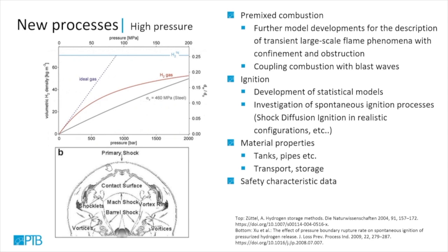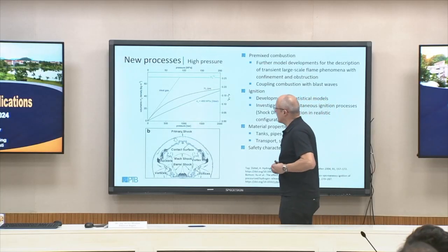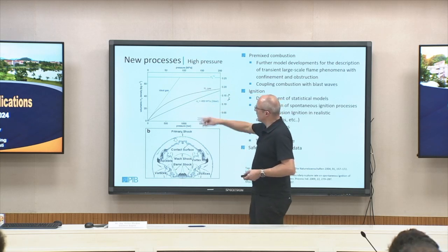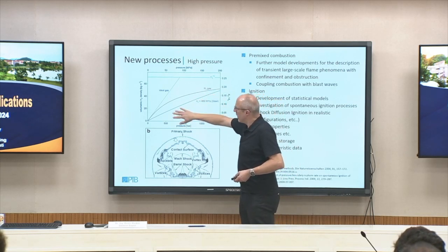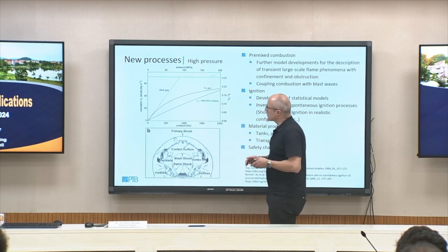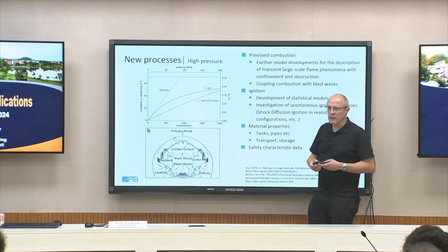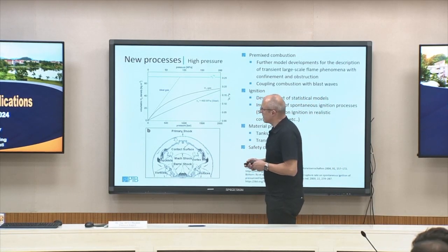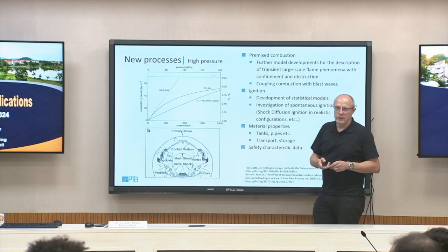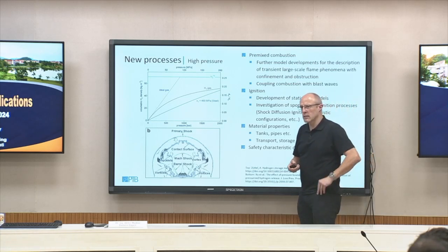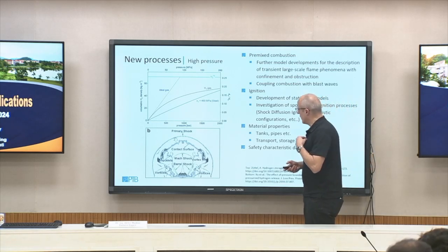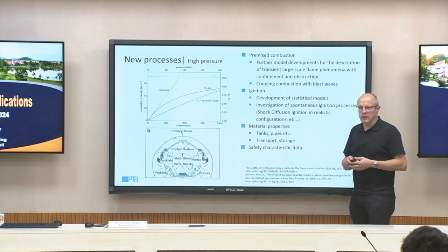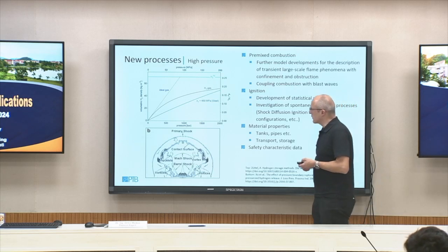So when you have this hydrogen in high pressure tanks, the advantage is it's no longer an ideal gas, and you can store much more hydrogen at specific conditions compared to an ideal gas. So that's the advantage. So again, 700 bar is the aim for the transport sector. So at the filling station, we talk about 1000 bar for a short time, and storage with 700 bar.